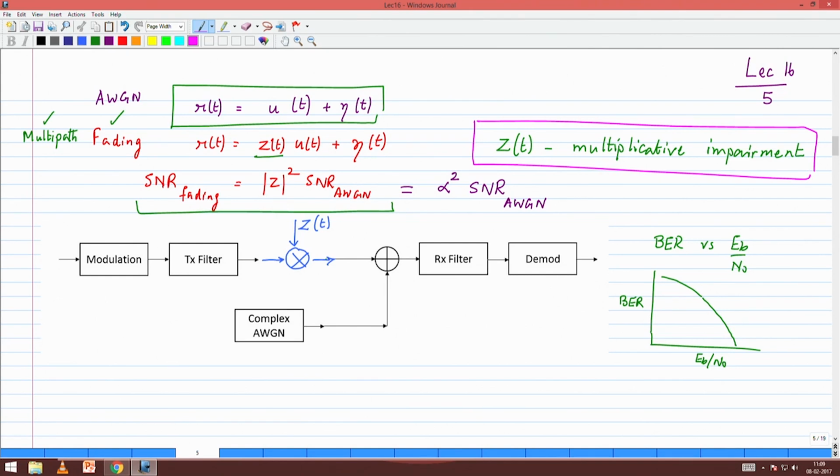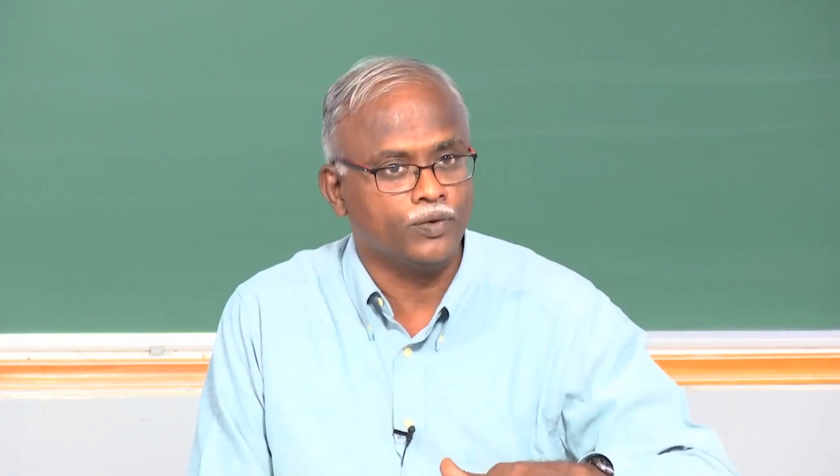So again, it's very important that we keep in mind the sequence, because this is where z(t) is happening in the channel. Basically z(t) gets multiplied. So all this says is when it comes to my receive side, even before the AWGN gets added, my signal is going up and down, and there is a possibility that the signal has gone down.